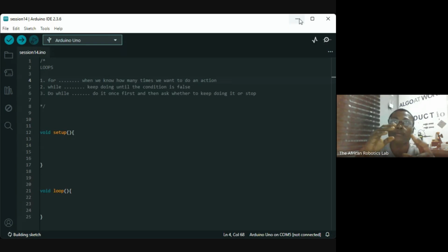So if you have about 5 sensors attached to just a 3.7 volt battery or a 5 volt battery, and you want your system to last for, let's say, a week before the user that purchased it charges it again. In that regard, you want to write some code. You want the system to measure the sensory data at certain times, right? So let's say at 12 p.m. in the afternoon, I want you to get the sensory data, so that the sensor is not always drawing current from morning to evening and wasting energy.